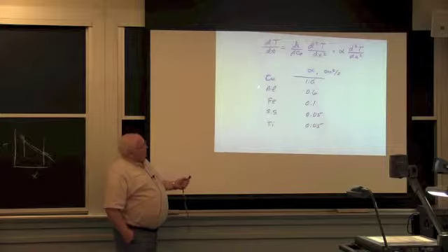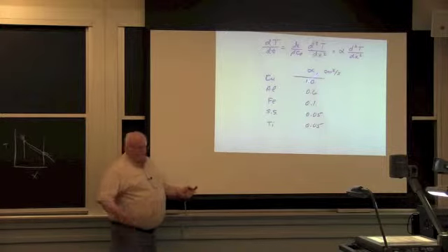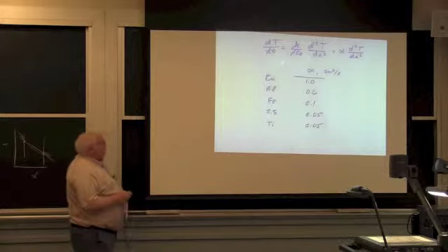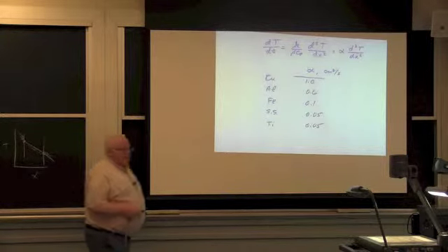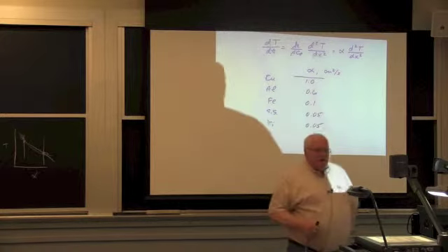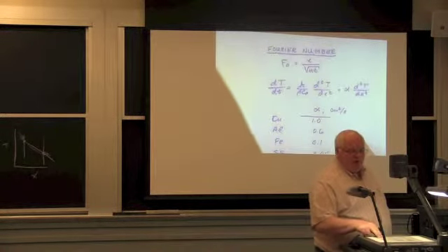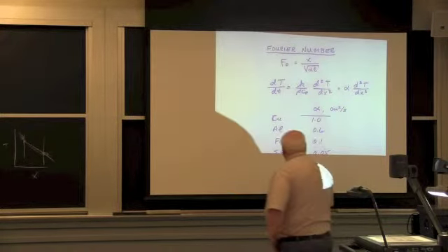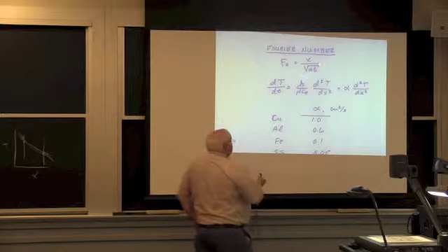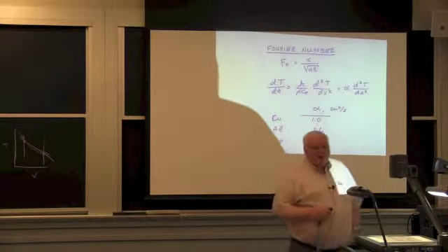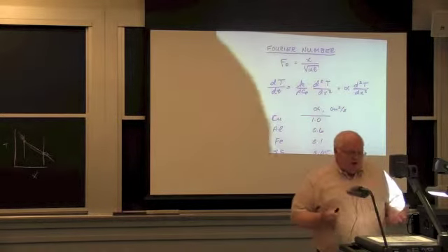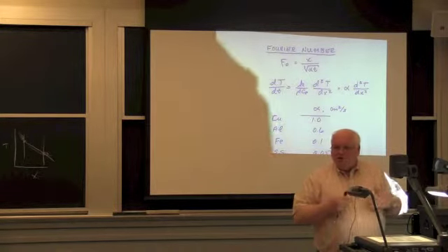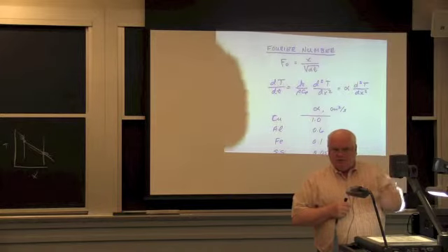And so Steve will tell you I don't like to solve equations or go do finite element analyses myself, but it turns out I can just take the Fourier number up here and I can solve 95% of all problems that I'm faced with. I'm talking about real engineering problems, not some homework problem, with this simple little formula of the Fourier number. And Einstein, I think, was the first one who proved mathematically that you always get an argument that's going to be x over the square root of the diffusivity times time.